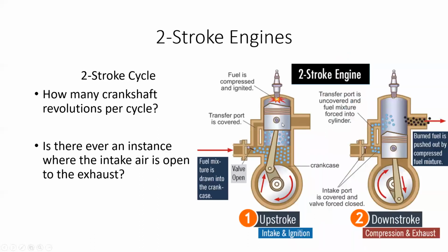This brings it all together. Again, the upstroke brings the fuel in underneath it, the downstroke transfers it around, and the upstroke is compressing it up here as well.